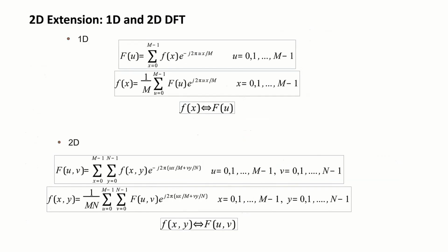This is enough. The definition of Fourier transform, now we have x because of discrete, and I move it to discrete in Fourier, so I represent it with the definition that I showed you. Okay, and this is a discrete Fourier transform with summation, multiplying with the exponential or sinusoids. Okay, and the inverse will be just the inverse with 1 over m. If I transform to 2D, I will have two summations from the x and y axis. So x will be from 0 to m minus 1, y will be 0 to n minus 1.